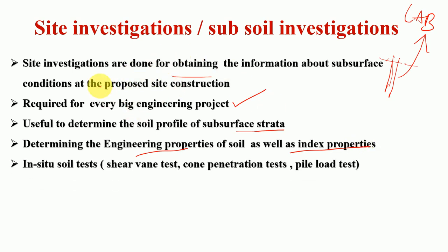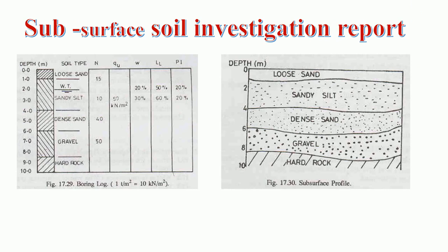Then, as a part of site investigation, we can also do in situ soil tests, like the shear vane test, cone penetration test, and pile load test. All these are in situ, meaning we don't do them in the laboratory; we can do the test in the site itself.